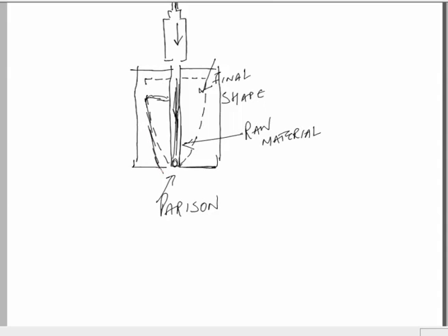It would inflate under the influence of the hot air which is blown inside and it would take this particular shape. So this is the raw material and the name suggests blow molding. Blow means we are blowing air and molding means that the raw material is taking the shape of the mold. So the mold is also clearly shown.